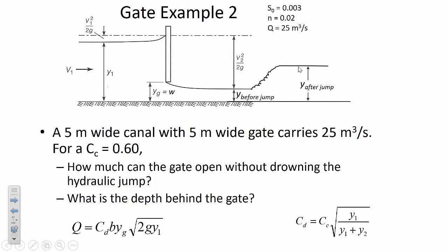That's the normal depth. And then calculate the critical depth for the second phase and see if a hydraulic jump can be supported. So in other words, compare Y sub C and Yn. And then the third thing will be to calculate the maximum gate opening. Let me write that on the board just to give you some outline of what you're doing.